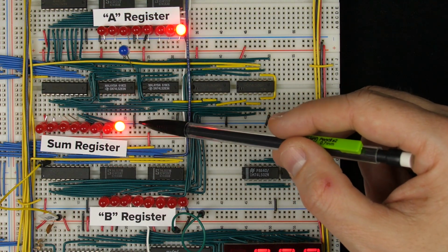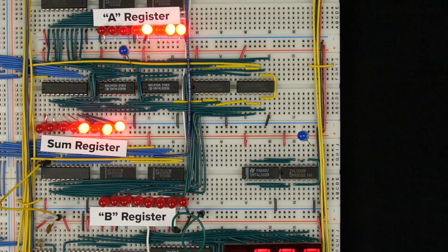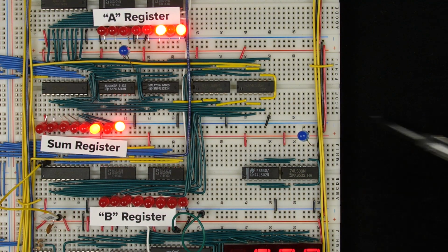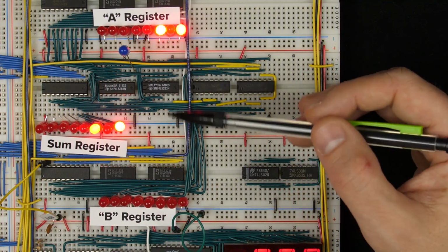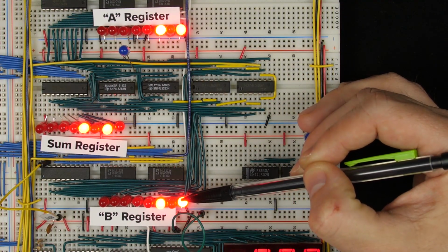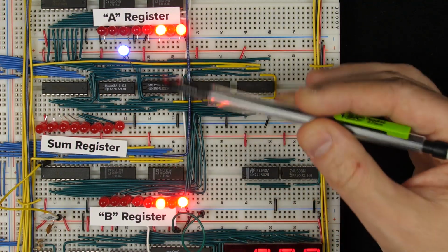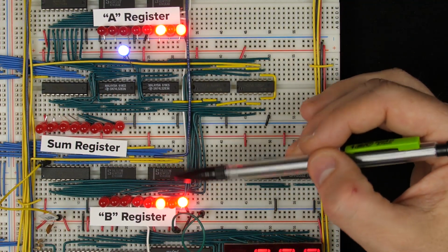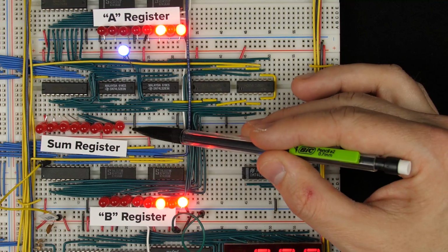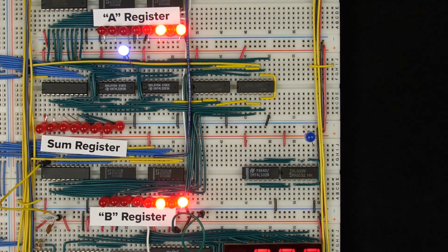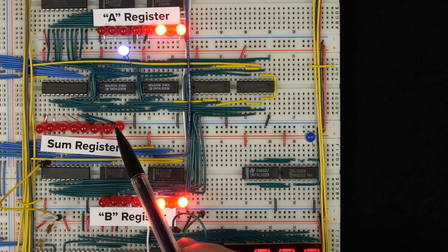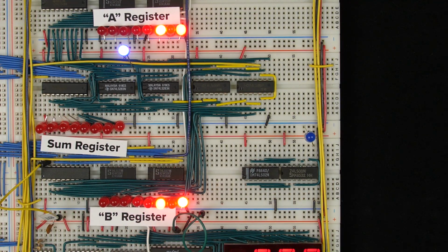But it also means if we wanted to, we could write microcode for even more conditional jump instructions, like jump if A equals a particular value. So for example, if we wanted to jump if A equals 5, like it does here, then we could put a 5 in the B register, turn on the subtract bit, so we're subtracting B from A, and since A equals B, when we subtract, we get a 0, and so we could jump if A equals 5. So hooking our new 0 detecting circuit up to the sum register is definitely the way to go, since I think it'll give us a lot more options.